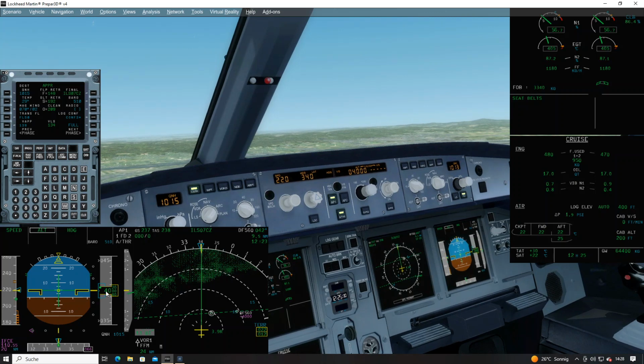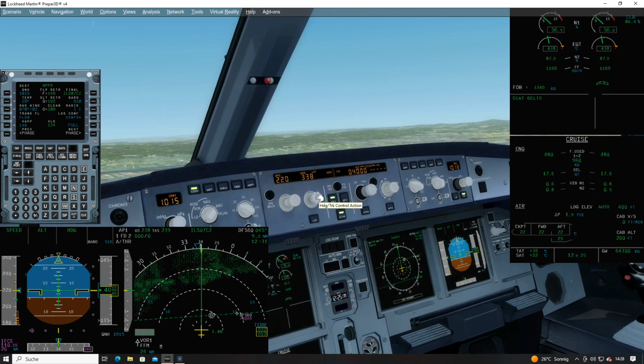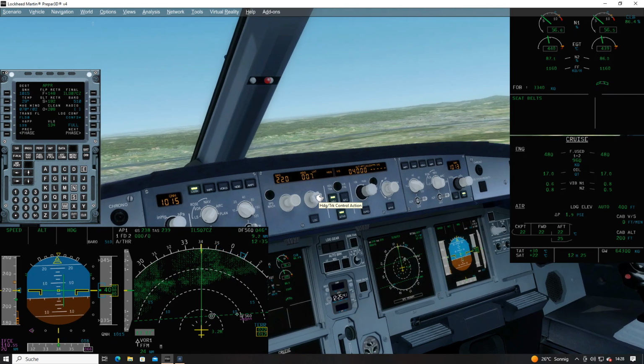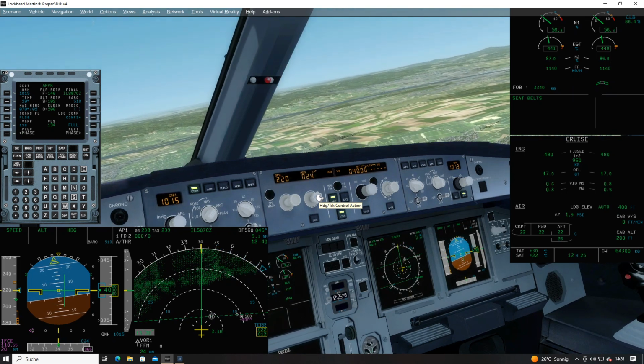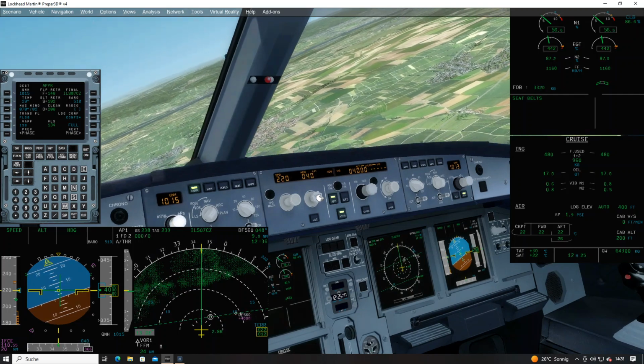Now we're at 4,000 feet. Still good. Heading inbound or course inbound Delta Fox 560 would be 43, 44, and increasing. So if I turn right now in this direction, on a heading of 040, we got the perfect intercept heading.